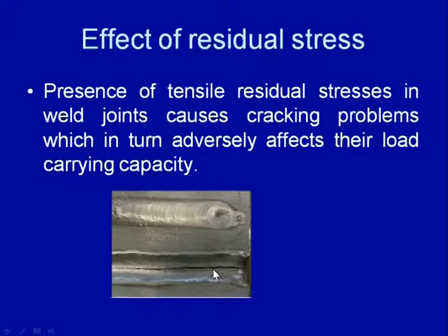So, this typical photograph shows a solidification crack developed along the length of the weld center line. This kind of crack primarily develops due to the presence of tensile residual stresses along the weld zone, and the presence of the residual stresses increases the cracking tendency. Further, these reduce the load carrying capacity, because no mechanical component with cracks can survive for long under tensile residual stress and tensile load conditions.